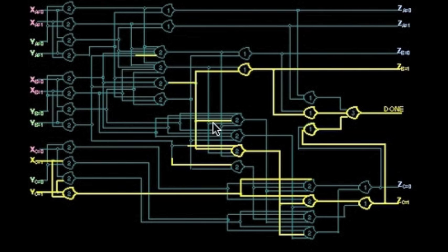And there are no transitions from null to data. There are only transitions from data to null. There are no incorrect transitions. There are no spurious transitions. And again, there are no glitches. So the null wavefront is flowing with full logical determination except for the orphan paths.